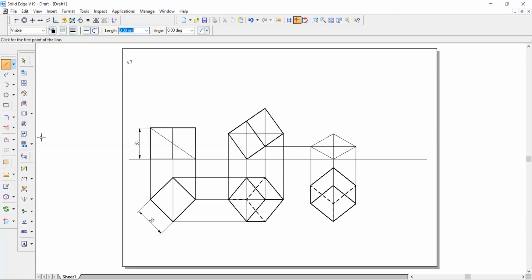Okay, next the top face you have to just again project. So project this. I know these two lines will be here somewhere, so I'll just project this. I know this is somewhere on the lines, but since it is a corner, both the corners will lie on the same line. If I just project this also, it's fine. So there are two particular lines. Again, see, there's no need of projection. This particular line only, if you just extend, you will get the other one. Okay, so similarly, this particular thing, if you extend, you will get the other one.